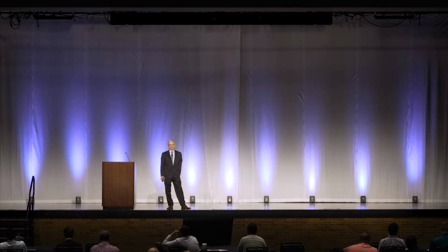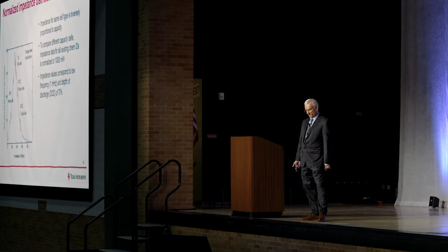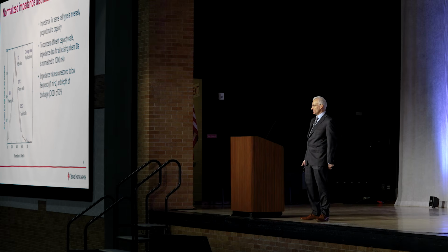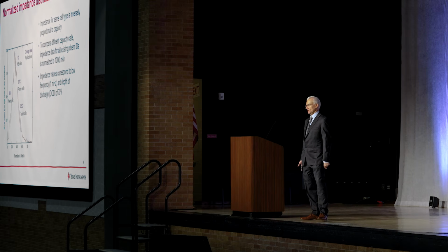On the other hand, for high power applications, you want to be below 100 milliohm. So typical power cells are around the 100 milliohm region. And if you are below that, then your cell is actually great. Then it is even better than originally intended. And some cells that are literally designed almost to be supercapacitors can be even below 50 milliohm.